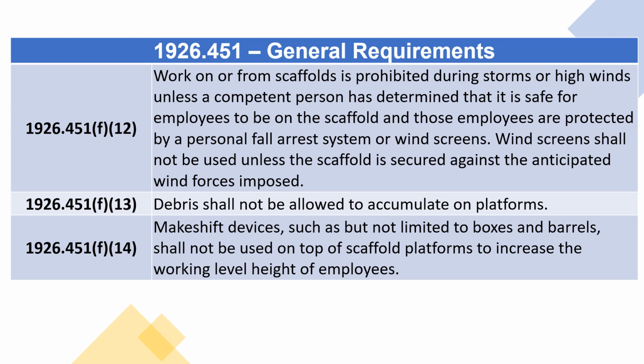1926.451(f)(13): Debris shall not be allowed to accumulate on platforms. 1926.451(f)(14): Makeshift devices, such as but not limited to boxes and barrels, shall not be used on top of scaffold platforms to increase the working level height of employees.